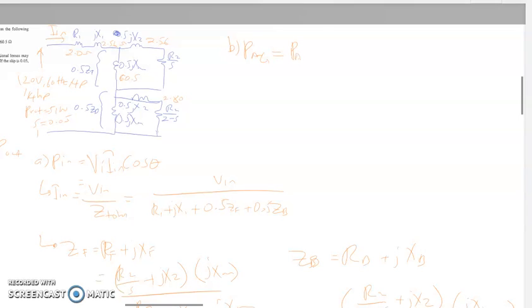So P air gap is equal to P air gap forward minus P air gap backward. The forward minus the backward. So we find out the first forward air gap power. So P equal to I squared R. Now the I is your input current times R, which is half of the resistance, the impedance, which is RF. So I squared times 0.5 RF.